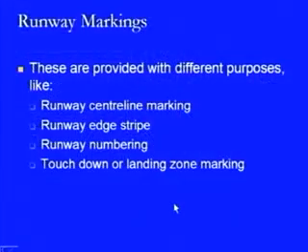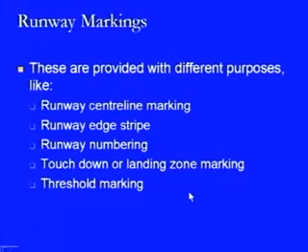So, that is the numbering of the runway strips, that all needs to be provided. Then, as we have been discussing the landing conditions, there is the touchdown zone, also known as the landing zone. For that reason, the marking showing where this landing zone or touchdown zone is needs to be provided. Then there is a threshold marking, which defines the specified height by which the aircraft should cross it, so that they can reach the touchdown point in a very safe condition.